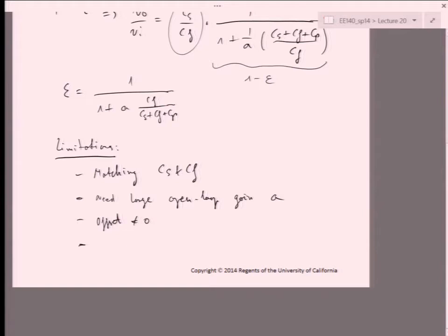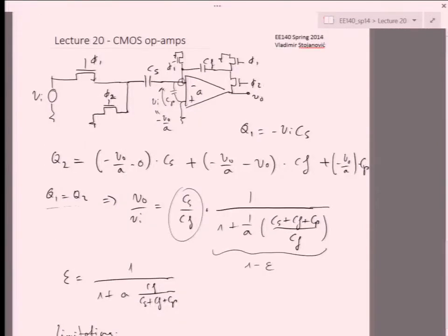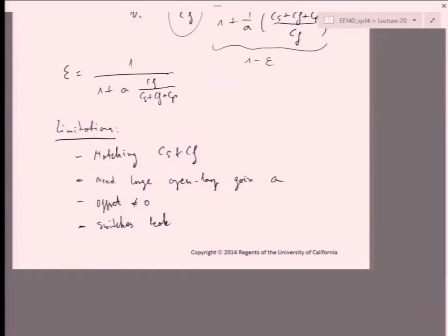Then we have some things like switches leak, especially in modern technology. When you turn off the switch, there's actually pretty substantial current still going through it. And that will limit our conservation of charge here. Okay, so it will introduce some error and make you have to go faster in charging and discharging the capacitance. So the leakage time compared to the time that you're really charging the capacitor is much smaller. And therefore, the total leaked out charge is small.